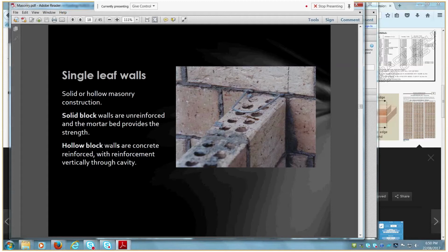So we've got a timber frame, but then within the garage, and you see it sometimes, where you've got your single leaf of brickwork. So this is our single leaf brickwork like this, and then little sections like this that protrude out, and the wall continues. Has everybody seen that in carports, etc.? So they're what are called engaged piers. And that basically provides a greater dimension to the wall to give it stability.